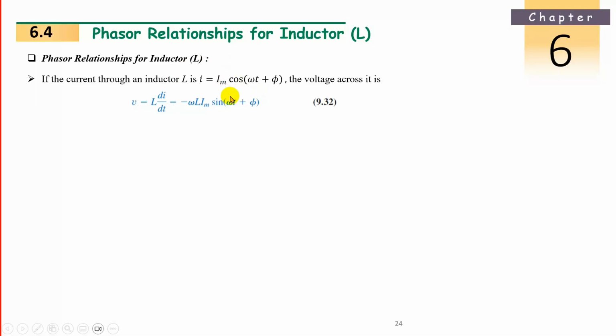Okay, so now it is okay. We can write sine as cos(omega t plus phi plus 90 degrees). But the problem is there is a minus sign outside that has to be taken care of. That has to be a positive term. So minus sin A is nothing but cos A plus 90 degrees.